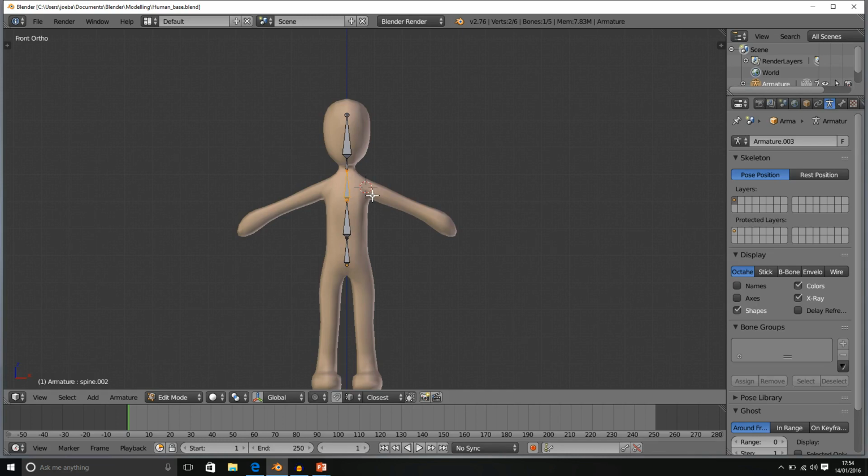So now I'm going to press Shift A, and what that has done, because I am in edit mode, is automatically create a bone. Why has it done this automatically? Well, because if we were in object mode and we were to add a bone, adding a bone would be our only option anyway. So instead of just taking us to the menu where we just click add bone, it just adds it for us.